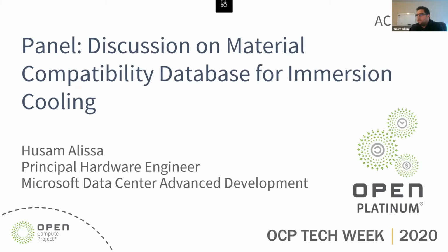One thing I wanted to mention when it comes to certification and material compatibility for immersion is that this really isn't unique to liquid immersion technology. If you look at it historically, we've been doing material compatibility qualification and testing for air cooling. A very famous example is board coating and material selection, dealing with airborne contaminants and moisture, and trying to select the appropriate set of materials to avoid creep corrosion, for instance.